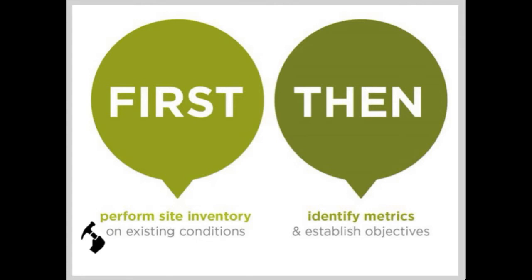Step 3 is to perform site inventory by gathering information and developing an inventory of current site conditions. This includes creating a site map that identifies each area on the site and shows the currently vegetated areas. The next step is to use the inventory and the information gathered by the site team to define site improvement goals and objectives. This is when the team should address a variety of site concerns, including maintenance activities, watershed quality, soil quality, community congregation areas, plant types and vegetation palette, and exterior design strategies.